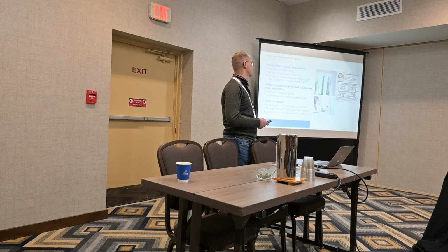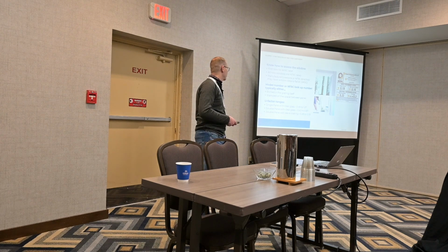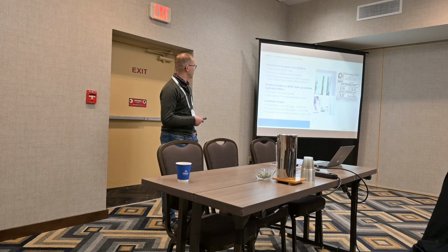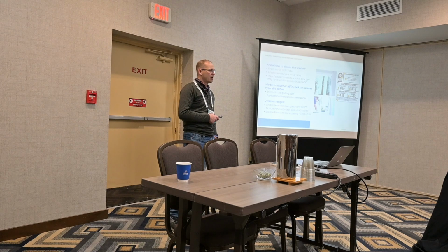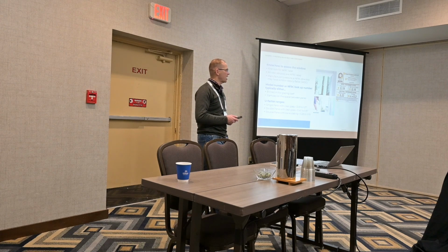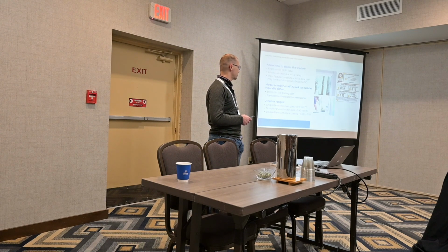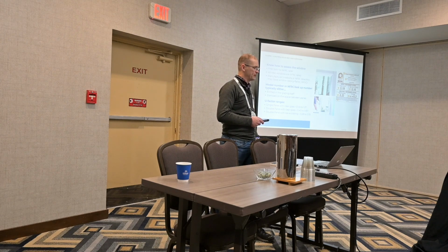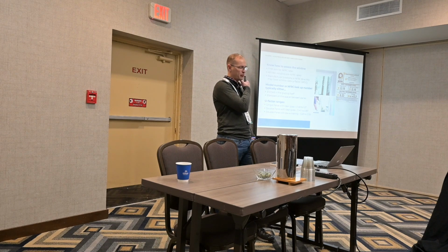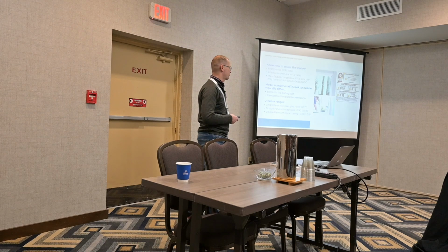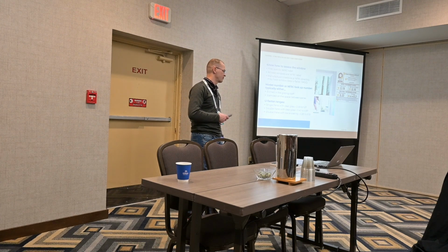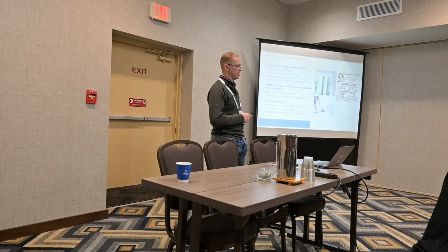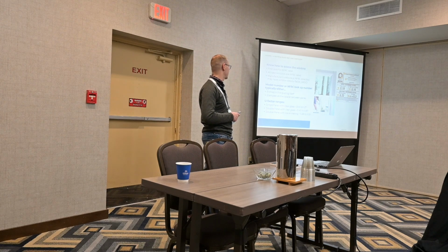Get the U-factors. Model numbers for the lookup are typically either etched, like I said, or stamped in between the window panes. And then if you're having a hard time with that, here are U-factor ranges, and these are a little conservative. Single pane is 0.49 to pretty high above 1, essentially allowing heat to move past it as if it's not there.